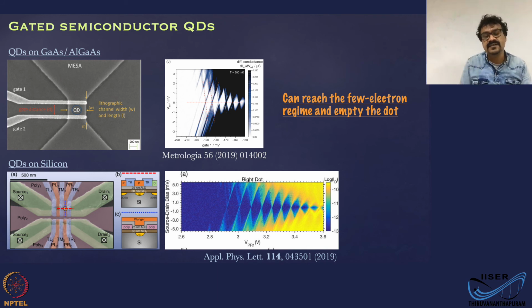Second, quite often you define this semiconductor quantum dot by gating. Metallic quantum dots are defined not by gating. Those are basically made by making the island smaller by various techniques, which we will discuss in one of the coming classes, on how to make these devices. So the metallic quantum dots are actually small islands. Semiconductor quantum dots in general are defined by gating techniques.